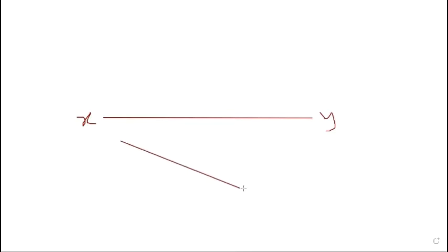Now in this problem, it is given that the line GH, 50 millimeter long, is inclined to the VP. So first we draw the XY line. Now here the point GH is not mentioned, so you can draw from this XY line, or you may leave some gap. So this is X, this is Y. Now in the top view we draw a line at 45 degree with this XY line and measure 50 millimeter. So first we draw a line at 45 degree and measure 50 millimeter.